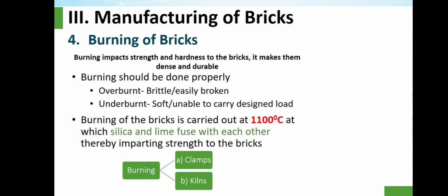Fourth, burning of bricks. Burning imparts strength and hardness to the bricks. It makes them dense and durable. Burning should be done properly. Overburnt bricks are brittle or easily broken. Underburnt bricks are soft or unable to carry designed load.